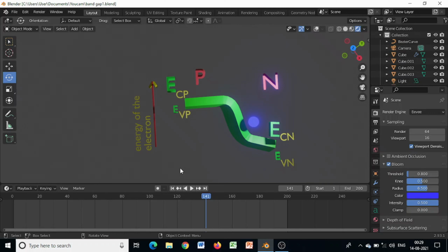So I am repeating this: for the tunneling of an electron from the p side valence band to the n side conduction band, it is also required that occupied energy states exist on the side from which the electron tunnels.